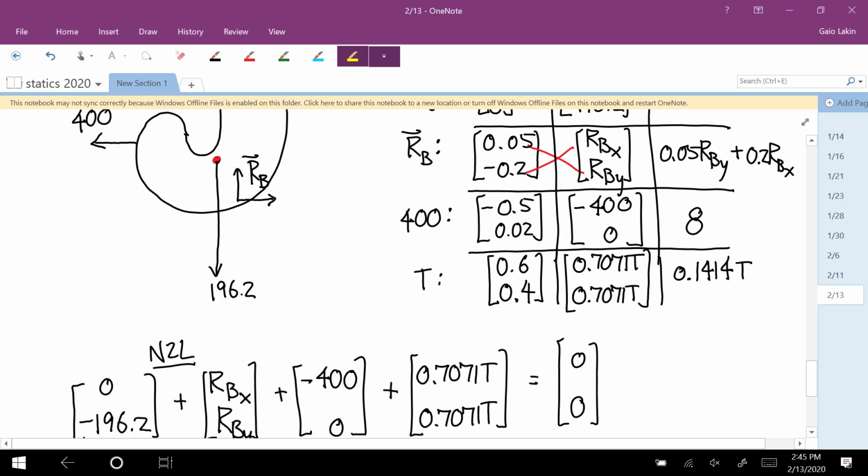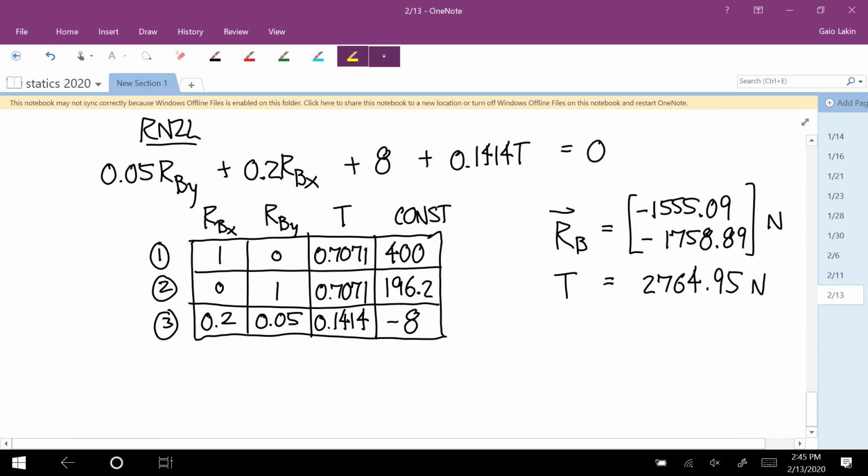There's one sanity check you can do on this one. You know that cable tension has to be positive, because with cable forces we always know the direction. So if that came out negative, something either went wrong with the calculation, or in the design. If you did all the steps right and it calculated that the cable was going to have to push on the thing, then the way you're setting up this structure isn't going to work.